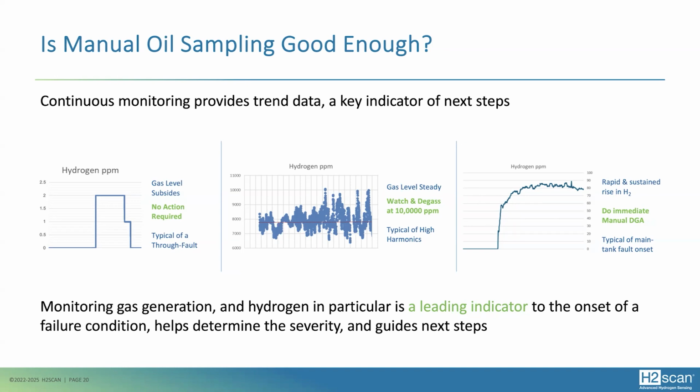So let's look at the very first one. This particular customer, they saw this rapid rise in gas. Okay, it didn't go very high, but it was still very rapid. And in our world, we do like to look not only at the level of the hydrogen, we like to look at the rate of change. And so the first response was, "Wow, this is quick. This rate of change is high." And there was an initial concern.